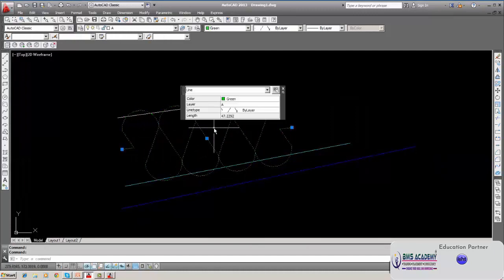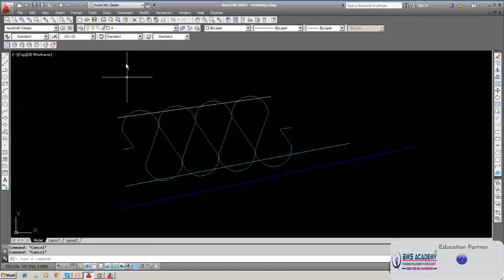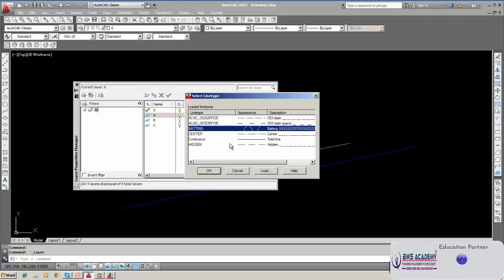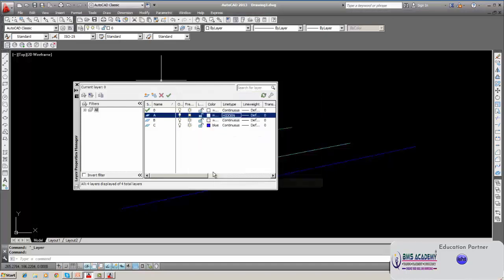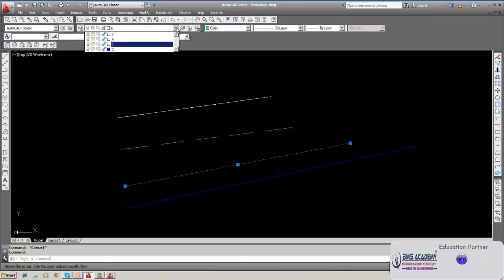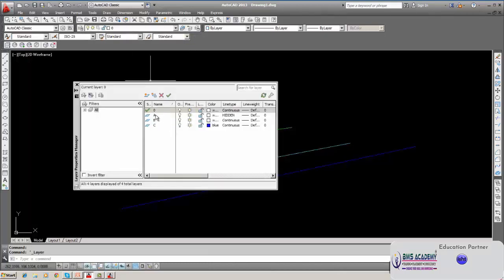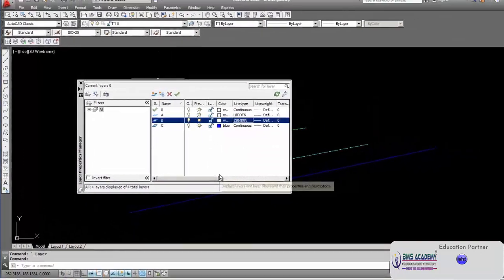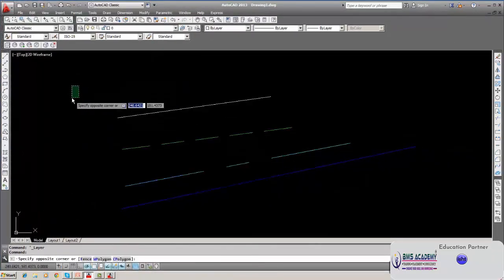It's very awkward. Anyway, we can change the layer to the original, or any other type. Hidden we can make it. So it is hidden layer. And this I will make center. Click on this and click here. Oh, properties you have to click. Select the layer. You are selecting B. If you want to change it, make it center, click. Okay, so it is changed.